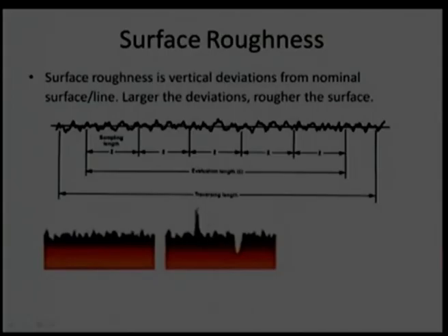But this is again at the start only. If there is a possibility of fracture of this sharp peak at the start itself, then there is no problem, and we can choose this surface as well. However, to implement this kind of approach, we generally use running-in time between the components. We know when we buy a new car or new automobile, generally the company instructs us to drive that vehicle at lower speed, so that the running-in or bedding-in time is over at the lower speed and does not cause a catastrophic failure.